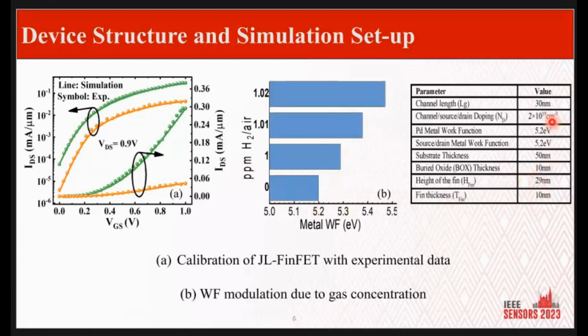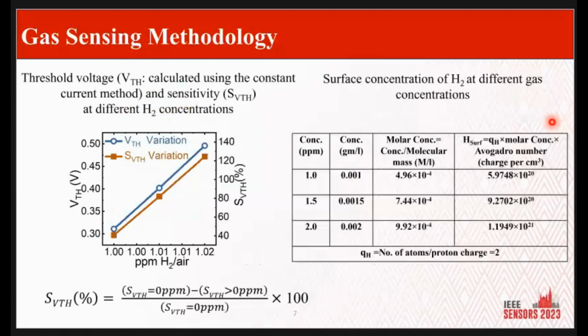And if we go into details, what you're going to see here is that basically we have a device which is 30 nanometers long, it's 10 nanometers wide, and 30 nanometers long. So this is what the device is. Literally looks like this. Okay, so we want to evaluate if this thing works. And what we did, or my colleagues did, they measured the voltage threshold. So the voltage threshold tells you, when you turn the device on and off, where exactly is the point that this device goes from off state to on state, which is from 0 bit to 1 bit.